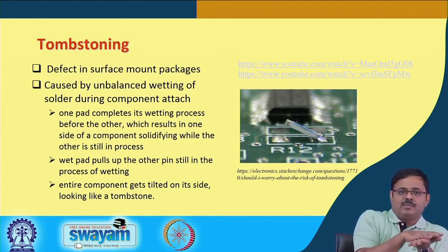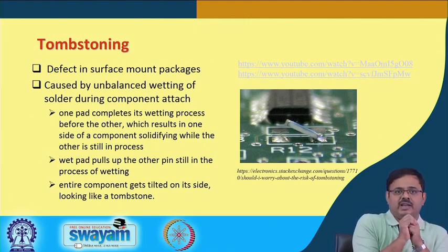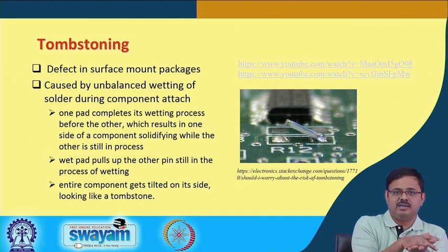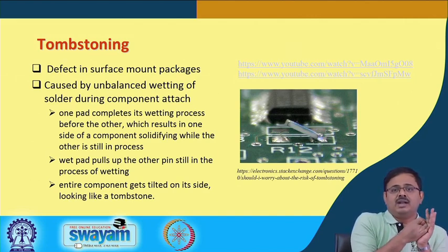Now, when this contact happens, when the solder melts, that is where the wetting happens. We call it solder wetting. That is essential for component attach, and then it has to solidify. Clear? Now, let us say one pad.